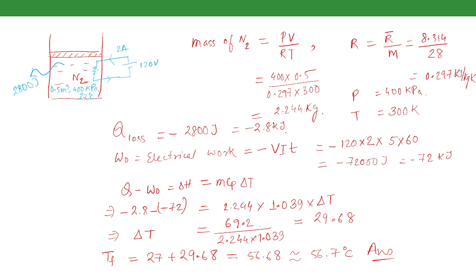Exactly, that is how you explain a quasi-static process. Supposedly if there are n number of weights placed on this piston and you remove the weights one by one, then it will start to expand. This will result in a decrease in the pressure. If we do not consider the heating part, and remove the weights one by one, then the volume will gradually increase and the pressure will gradually decrease. That is how we explain a quasi-static process.